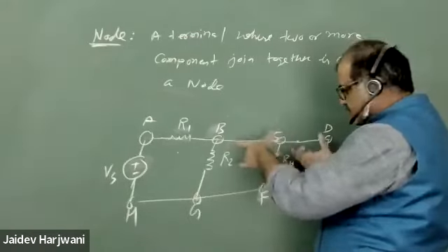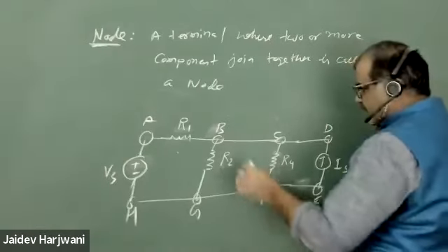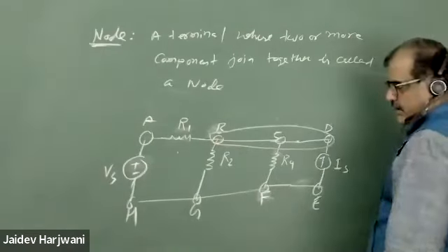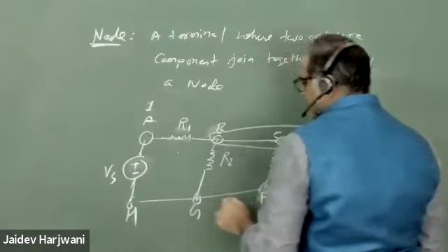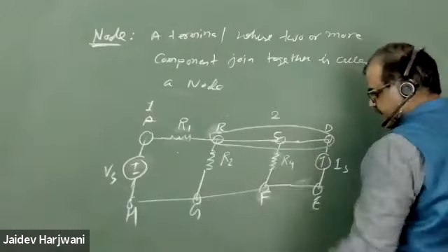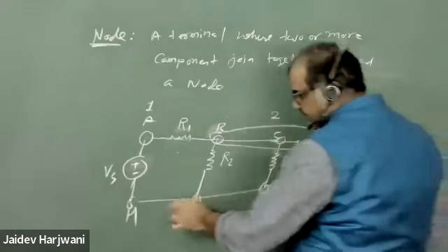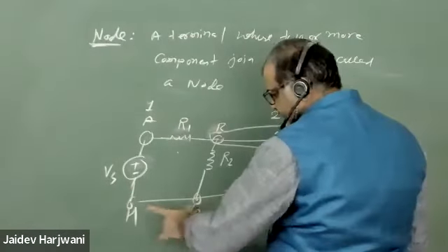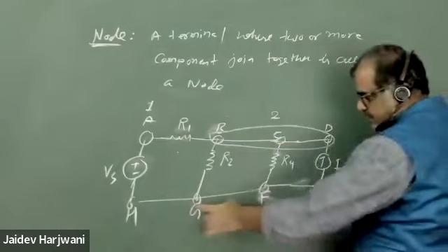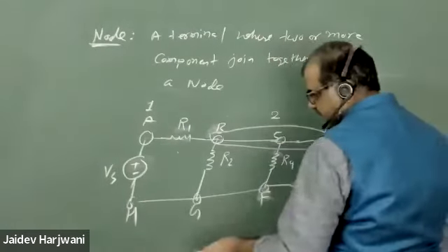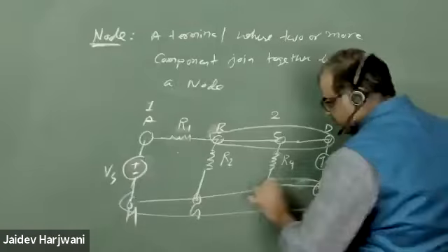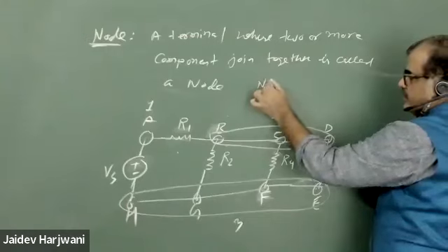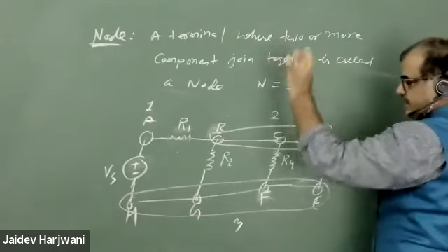Okay, just for representation, I am showing this wire. These all terminals, they are common, and they will make a single node. So I have one node here, this second node, and similarly these four terminals also have a common potential. They are just connected by zero resistance wires, so all of these also form a single node. So in this circuit, the number of nodes is only 3.